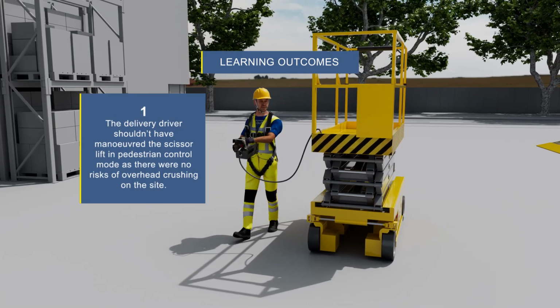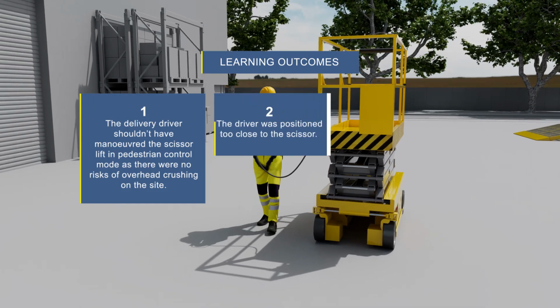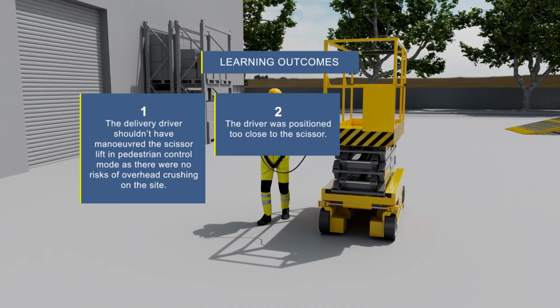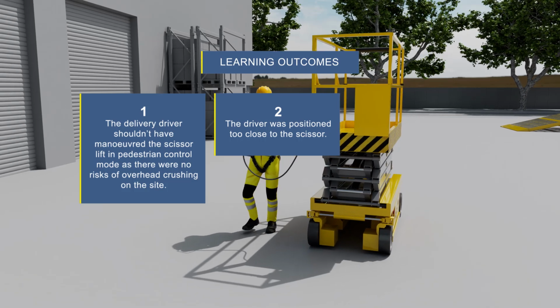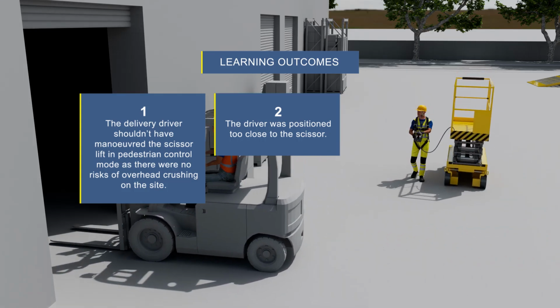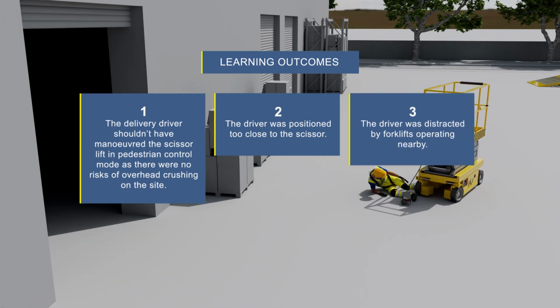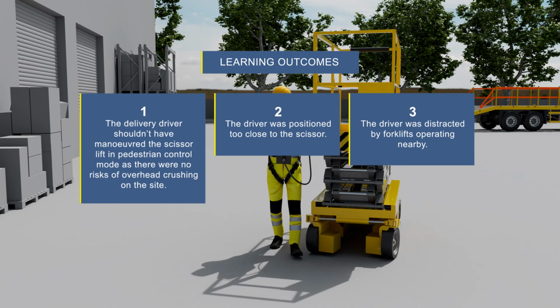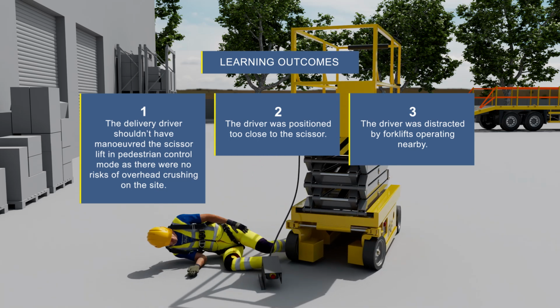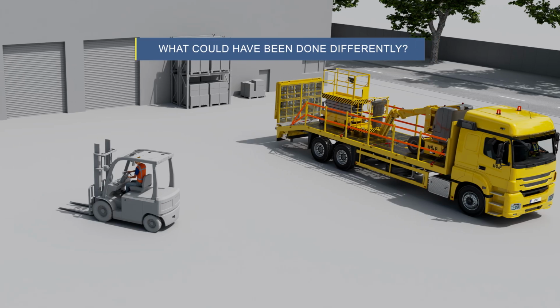The key learning outcomes of this incident are: the delivery driver shouldn't have maneuvered the scissor lift in pedestrian control mode, as there were no risks of overhead crushing on the site. There was no need to maneuver the mobile elevating work platform using the pedestrian controls, and the driver wasn't continuously observing the scissor and stood too close to it. The site was busy, with 2 forklifts operating nearby. The driver was distracted and not fully focused on moving the mobile elevating work platform.